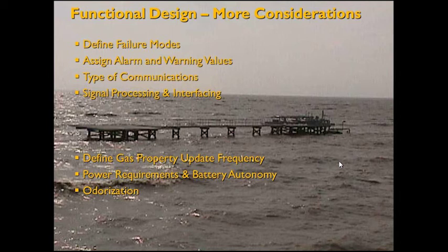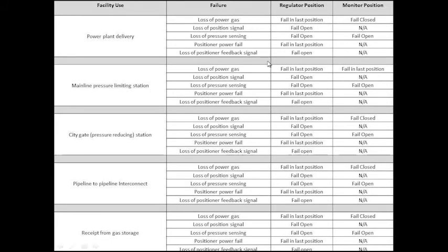In an environment like this, where we have this platform, power requirements are a particular concern. Certainly this equipment is all battery operated, charged with solar panels. And in an offshore environment, you want to have about 21 days of battery autonomy. Usually in 21 days, in the winter in particular, is when offshore it becomes very cloudy. Usually there's a time in there where you can get a few days of charge time in.